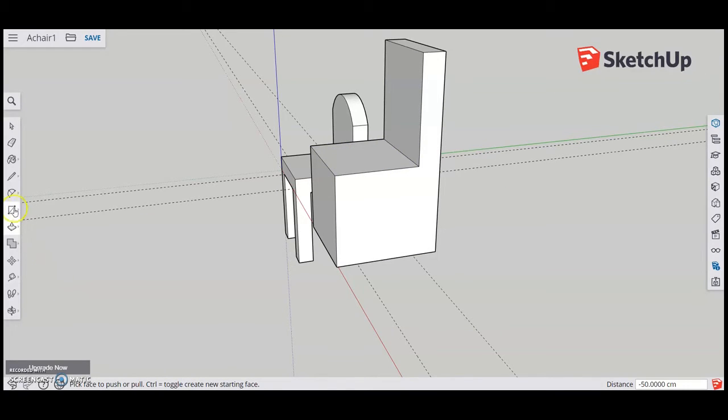Next, we're going to need two more rectangles. One is going to represent the void that is going to create our legs here on the bottom. So remember, in this case, another cool trick that's built in is if you hover to a point and then back away, it gives us an inference line. So it shows us this dotted line to show us that we're lined up or aligned in the right direction. So click once, and now we have this space here.